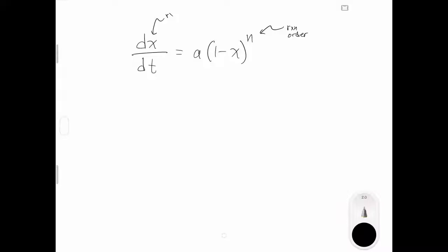Typically, x is defined as the reaction conversion, so how much conversion has occurred. 0 being pure reactants, and 1 being no more reactants are there. All of it has been converted. And t is time. That's used for batch processes where the system changes over time, but this dt term can be replaced by dV or dW, V for volume, W for weight, if you are studying a non-batch process, like a plug flow reactor or packed bed reactor respectively.